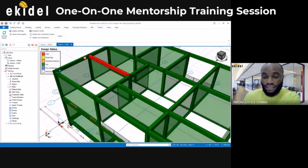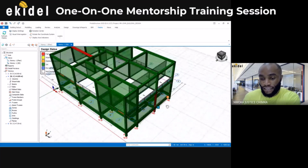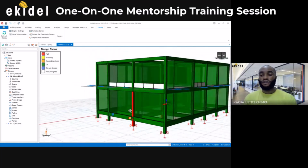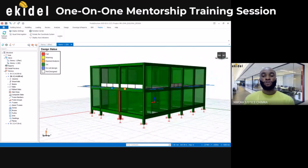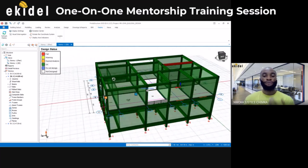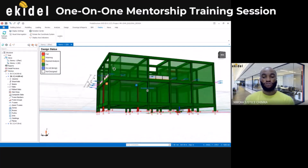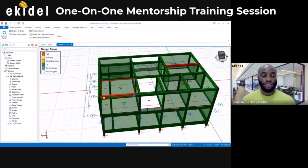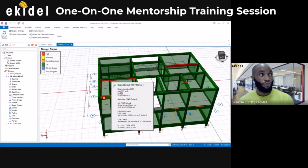For example, this beam here is failing, and then the column also. One column here is failing. Yeah. You can see that it's failing. Exactly. So even if they are all showing green, you still need to check the software to see what kind of reinforcement was used. So you need to check everything again: the ones that are green, the ones that are yellow, and anything else. Make sure you check all the members to be sure of the reinforcement that you're having.